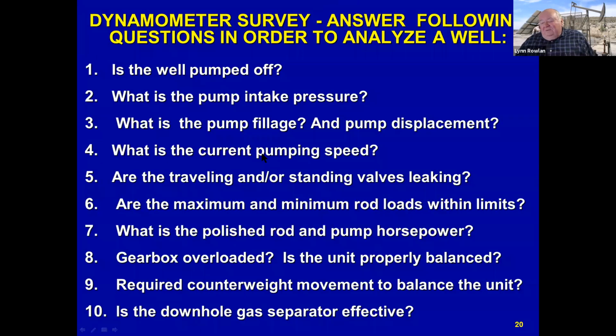Now, we also talked about the device that you can weigh yourself with, but we're going to weigh the rod string. It's called a dynamometer. And then we use the load we weigh, the weight of the rods at the surface along with the pump load. We use that load at the surface that we measure along with the position of the polish rod, which we determine from an accelerometer.